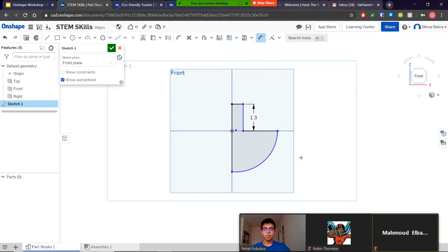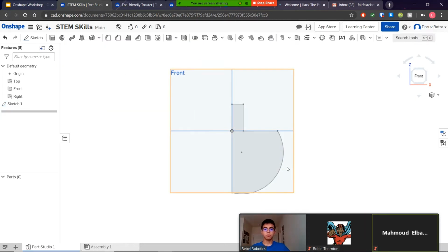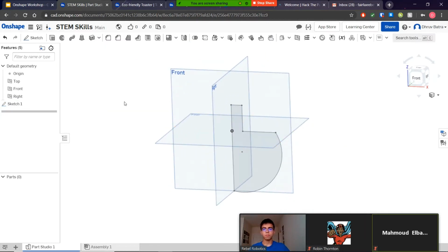If I make a sketch and it's like, oh wait, I need to dimension so that this specific area is, like, a specific length, I can just change that to 3, and it will manipulate the other parts of it so it matches your dimensions. So sometimes it'll give you an error if you have conflicting dimensions. What you have to do if you encounter that is you just have to delete one of them. And if you are really trying to go for something, you have to just try to dimension in a different way.